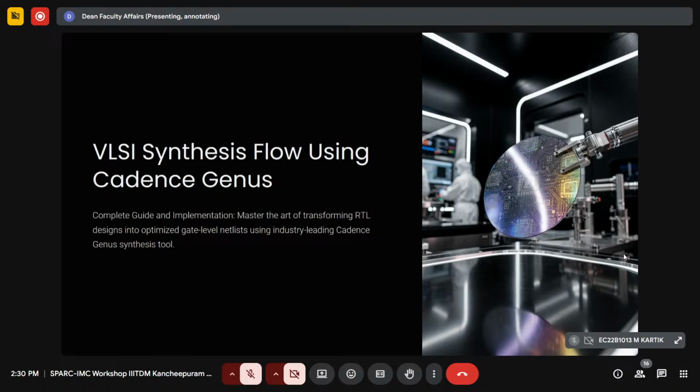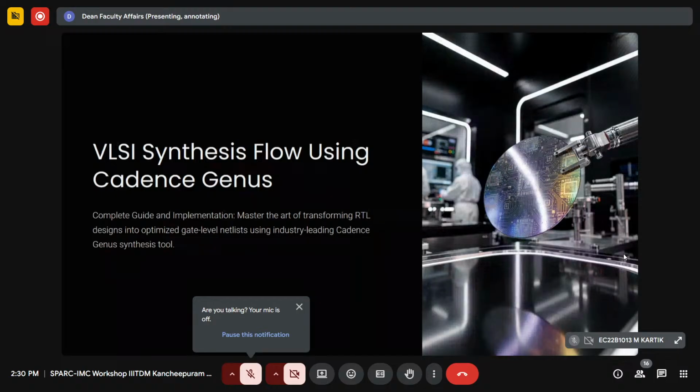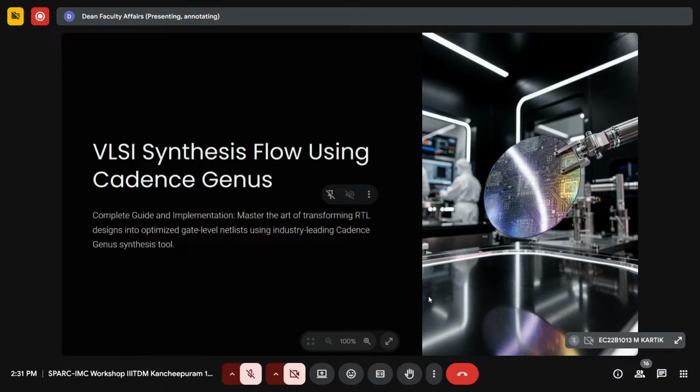The reason is the low metal layer always has a high resistance. Okay, if you see the technology file in any library, the low metal layer will have high resistance, whereas the high metal layer has low resistance. So when you design power, you obviously need to design using the high metal layer so that you get less resistance, right? All these will be pretty confusing, but put together, the physical information of the particular metal is present in the PDK file. That is, we call it the technology file, right?